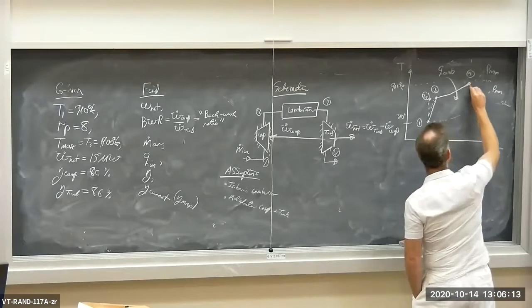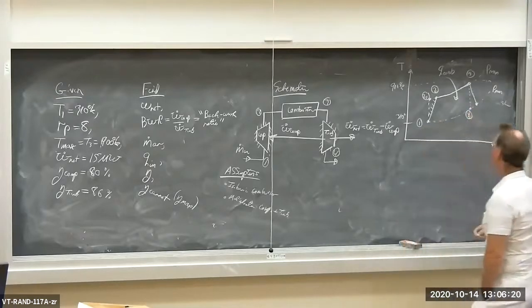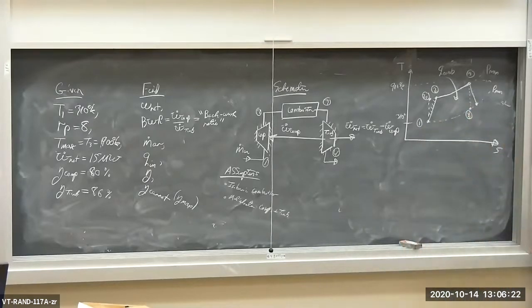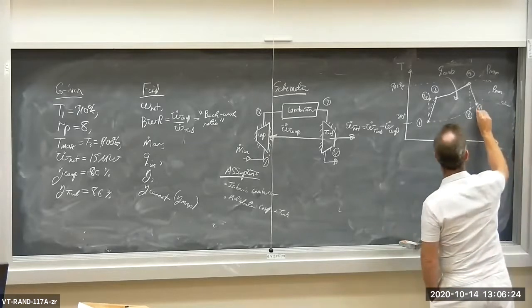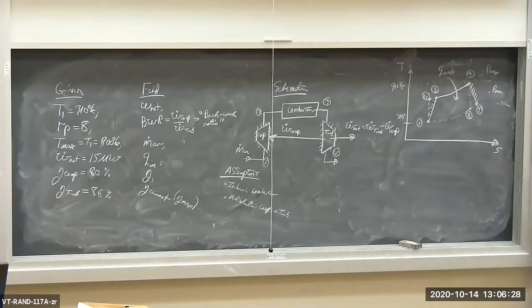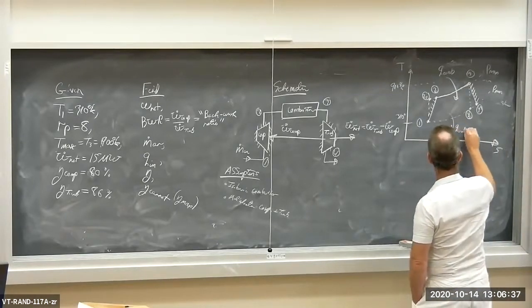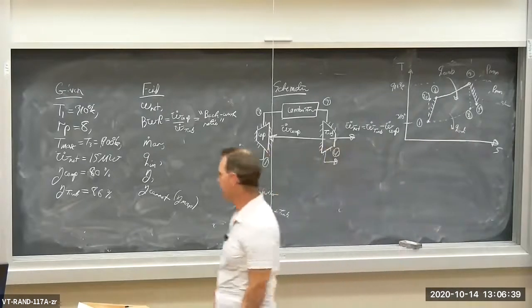It's going to be irreversible, so there's going to be a delta S compared to the isentropic expansion process. So we expand from state 3 to state 4. There's a positive delta S because we have entropy generation, and therefore delta S is positive through the turbine. And then we have the heat rejection process going on in the environment.